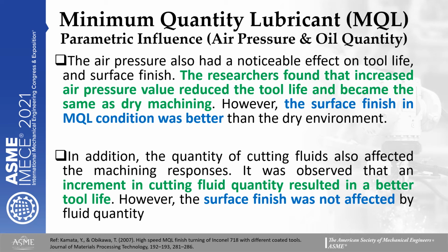The quantity of cutting fluid also affected the machining response. It was observed that an increment in cutting fluid quantity resulted in a better tool life. However, the surface finish was not affected by the fluid quantity.